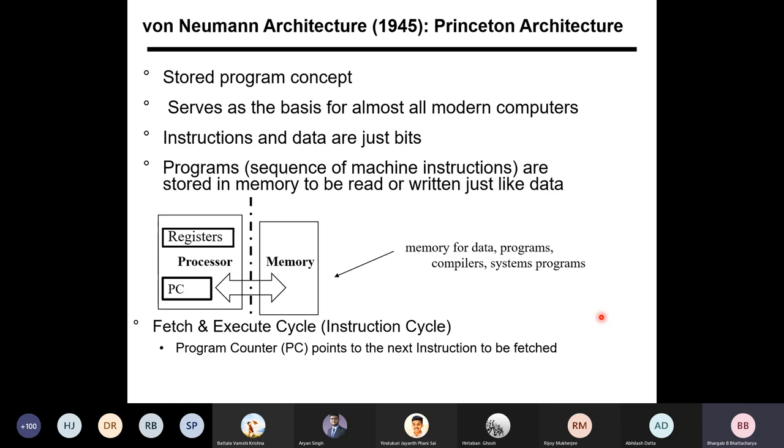Because I know that once this instruction is finished, the next instruction stays in the consecutive location in memory, which is 4 bytes apart from the first one. So therefore, the PC must be incremented by 4 bytes, and it would point to the next instruction. And the sequence is repeated. Are you with me?